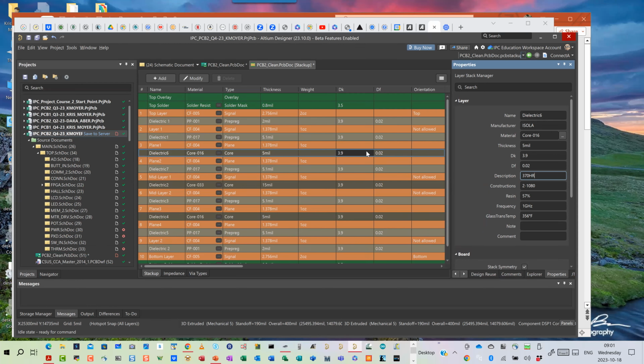So we're going to go over here. I'm going to create this. So now I have created my stack up here. I've gone from an 8-layer to a 10-layer because I've added this extra thin 2-layer out here. I've got signal, then plane, plane, signal, signal, plane, plane, and then my 2 bottommost signals here. Then there are these 2 other tabs down here at the bottom. I'm going to do the easier one first.